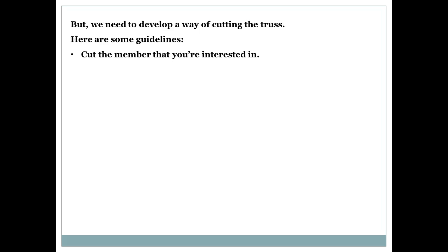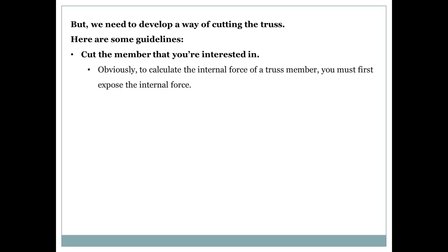But I'm going to teach you today how to cut the truss. I'm going to tell you the trick behind cutting a truss, the basic rules in cutting these members. Okay, the guidelines I'm going to talk about. First, obviously, cut the members that you are interested in. Remember, your first step is to go through the members you are interested in. It's an obvious thing to do because you want to expose the interior forces inside these members so you can calculate them.